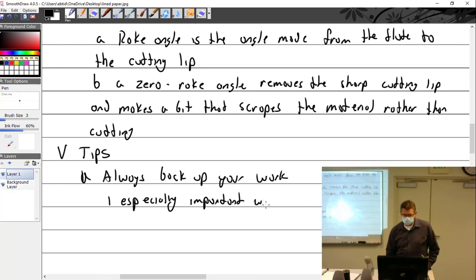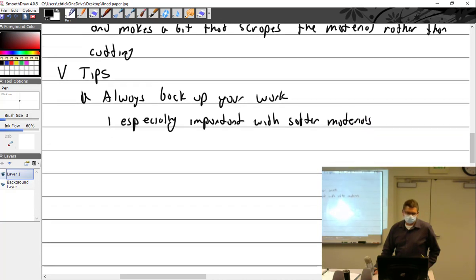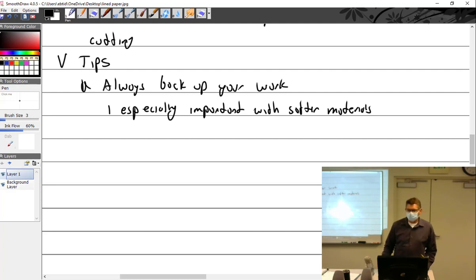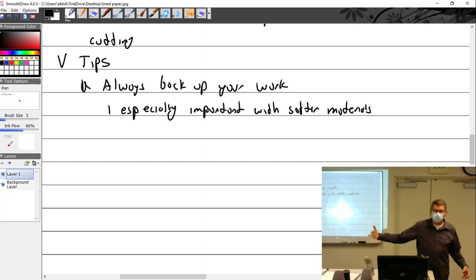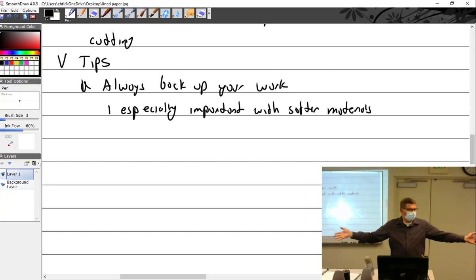It's especially important with softer materials. Not even so much, I'm talking like brass or plexiglass. If you're using a bit that doesn't have a zero rake angle and it actually does grab, it will tend to grab and actually pull the drill bit. Instead of you feeding it, it's going to pull the drill motor and you into the hole. And when it gets to the back side of that, it just blows it out. And so if you're doing a window, you'll actually blow out the back side of the window and have damage all over it. And it can get rather large. So that's just the beginning of the end of that window.